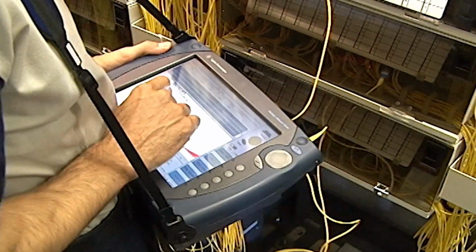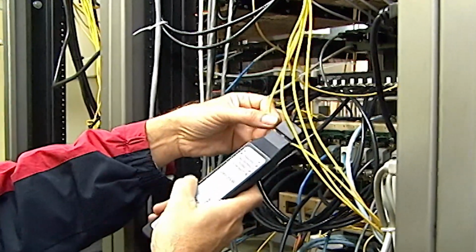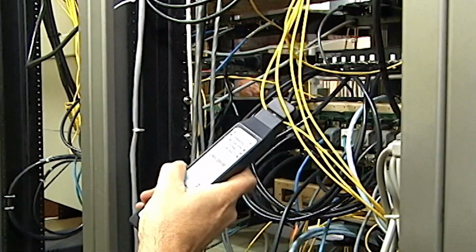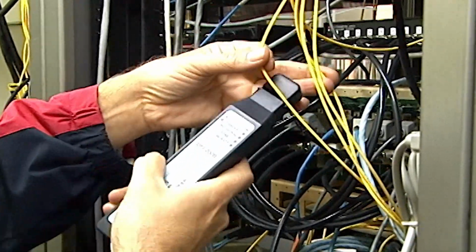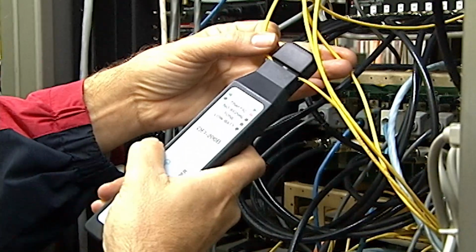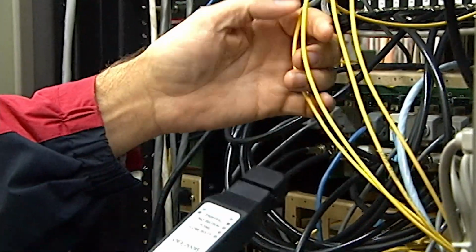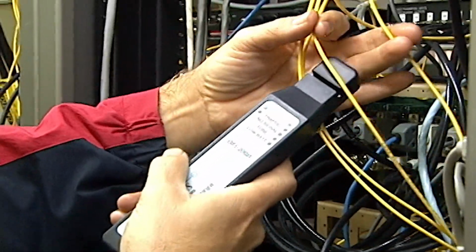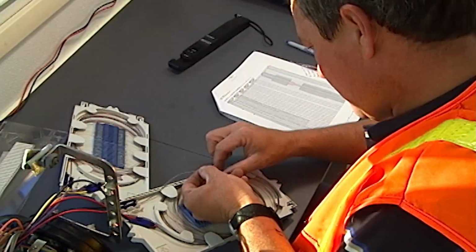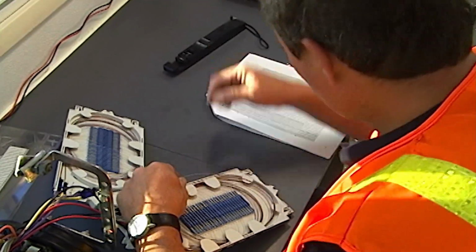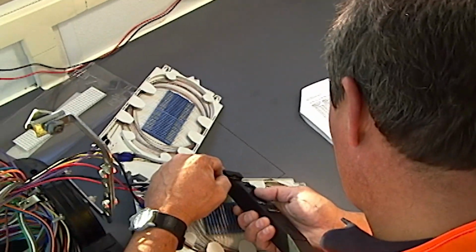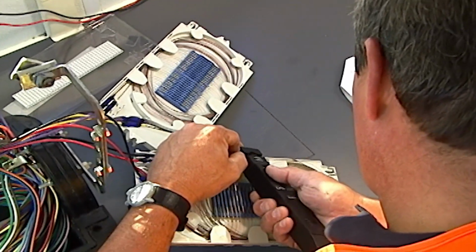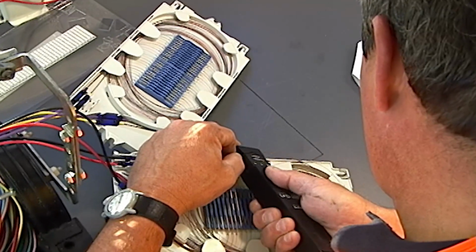Other useful instruments for fiber optic testing include fiber identifiers and visual tracers. The fiber identifier is a handheld instrument that determines if a fiber is currently carrying an optical signal and in which direction the signal is traveling. The fiber identifier is often used when performing mid-entries into multi-fiber cables where specific fibers must be accessed, providing assurance to network users and the technician that only the correct fibers will be cut.